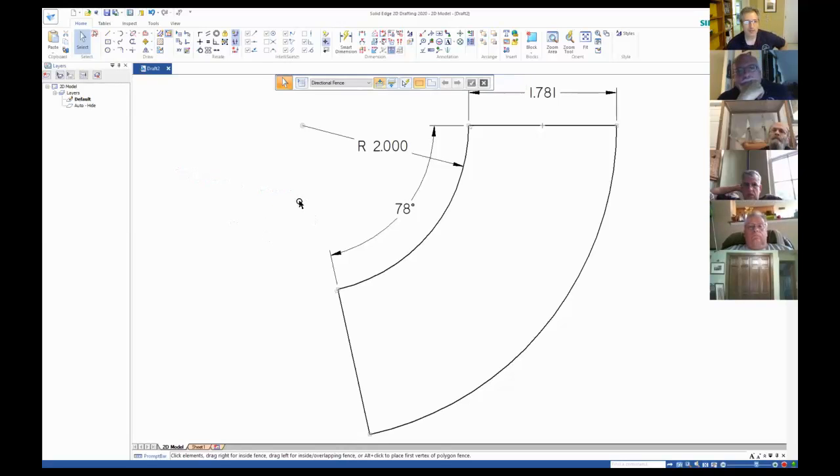And locked. Sometimes you want to keep something fixed as an unmovable reference. So if I draw a line and use the lock constraint, it is now fixed and can't move. And so now you see if I try and move this line, if I select it and drag it, it won't move because its end is connected to this one, and that one is not allowed to move.